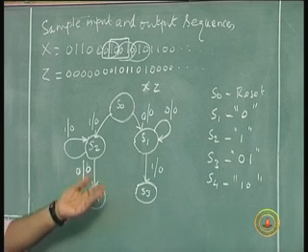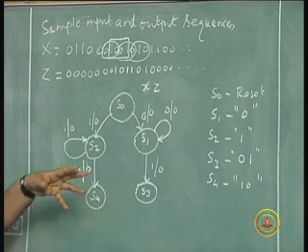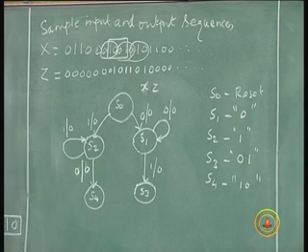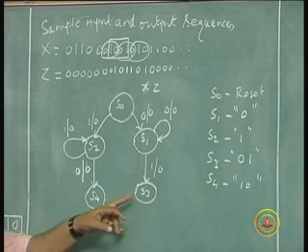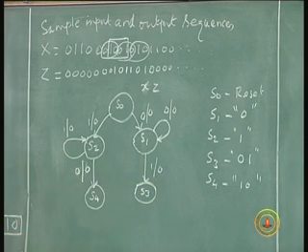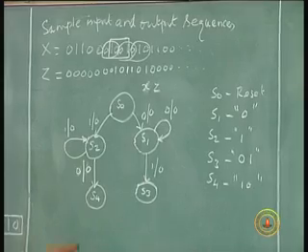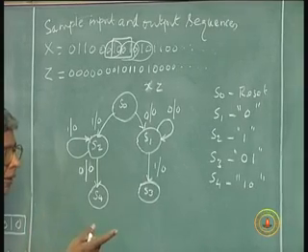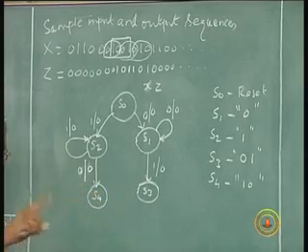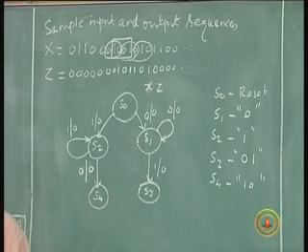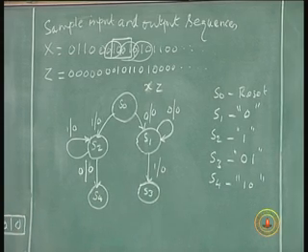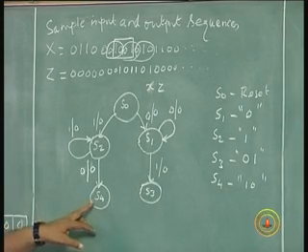So, you have to proceed like this for each state, until you have finished your patterns and no more possibility is there. So, in S3, 0 1, if a 0 occurs, the 0 1 0 pattern is completed, and that could also be part of 1 0. 0 1 0 could be the first 2 bits of a 1 0 0 1 pattern, which is already here in S4.